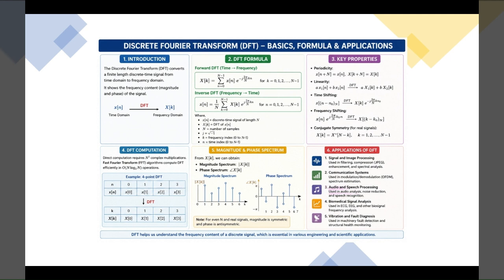So when you come to the computation for doing this mathematical operation on a signal, n squared complex multiplications are used by DFT. There is an advanced Fourier transform, the fast Fourier transform, where the computation is in the order of n log n. So here the number of computations gets reduced in fast Fourier transform.